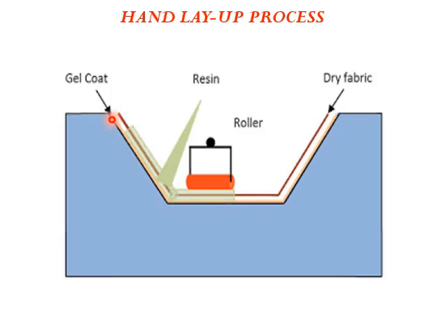Once the mold is designed according to the shape which you're going to get, the first thing is to have the surface of the mold covered with a gel coat. This is going to facilitate removing the end product easily, which will help to strip the final product from the mold surface easily.